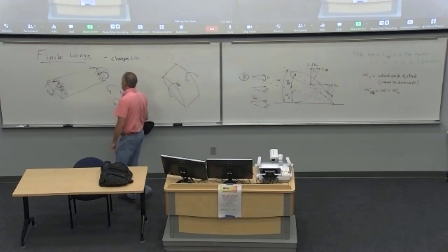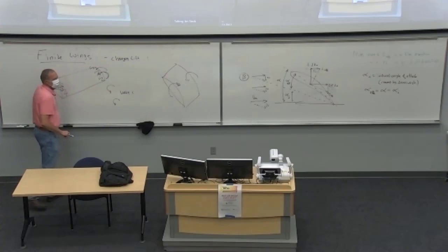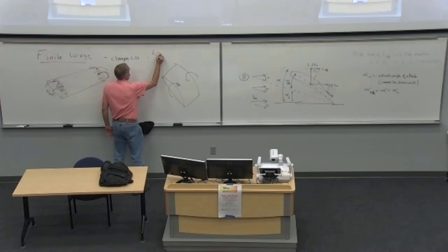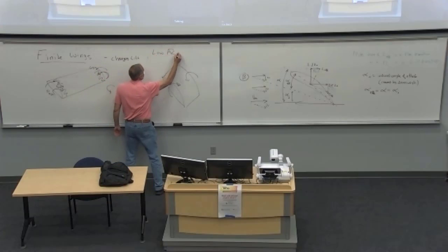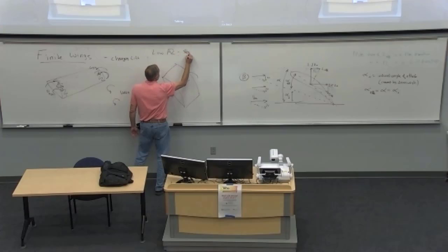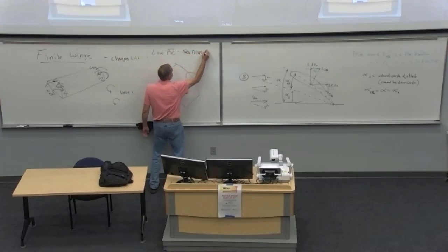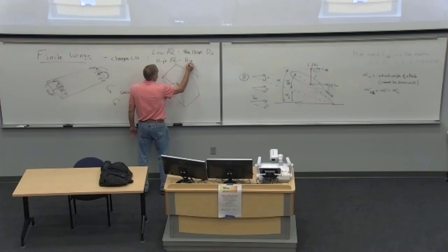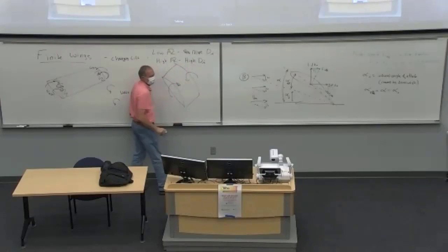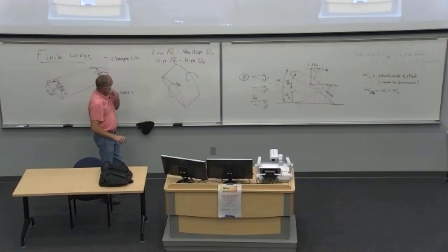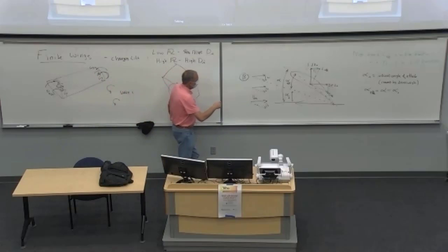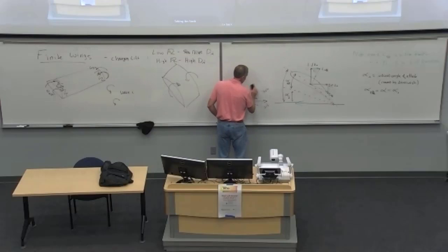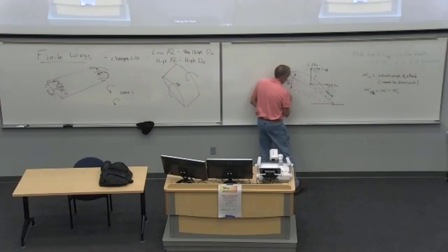So if you have a high aspect ratio, or a long wing, then you get less of the effect. So low aspect ratio, more induced drag; high aspect ratio, less induced drag. And so those are the formulas I'm going to give you that people have developed to model this effect.